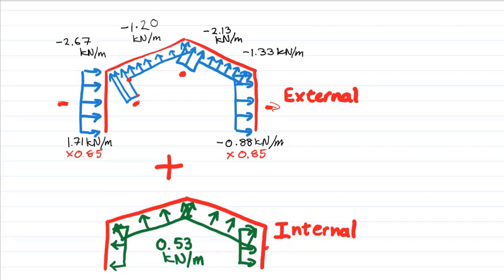We've only considered one specific case here with maximum pressure uplift, but you could have multiple cases with different CPI values, different CPE values, because you can also have cases where it goes up on one side and down on the other, etc. But as I mentioned earlier, this can give you 32, 64 and many more different cases, but normally a good structural engineer can look at this and break it down into a small number of wind cases that will govern the design, and then work with those in the rest of the combinations.